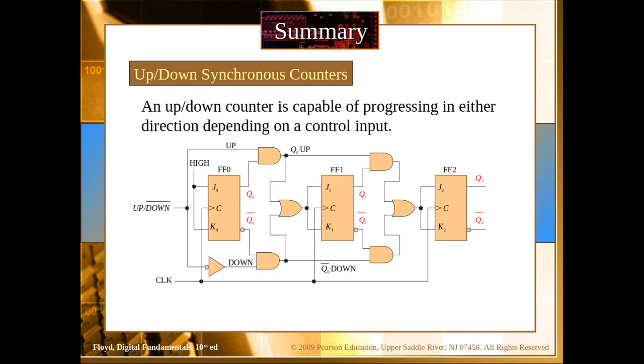Similarly to the counters that we have seen, where the count starts from 0 and goes to all ones, we call them up counters. We can also have down counters, where the count starts from all ones and the numbers are reduced by one number at a time. So for example, if it starts from 15, it reaches 0 ultimately, and then the backward counting would start again. So kind of like backward counting.